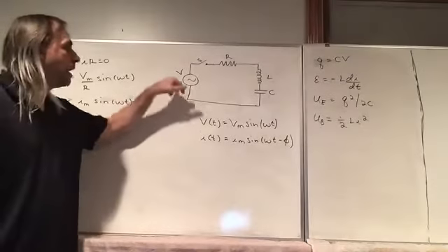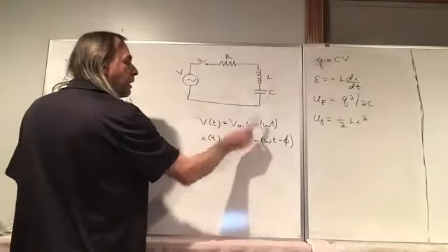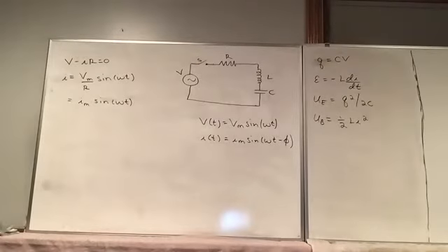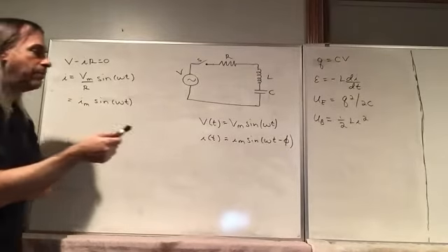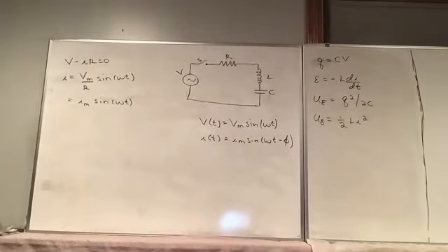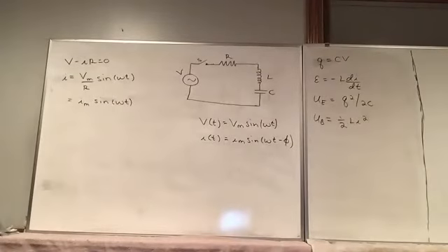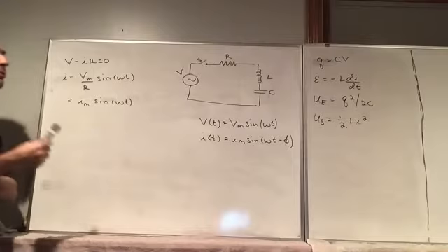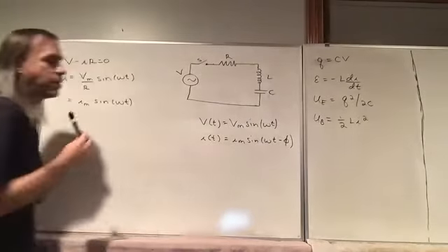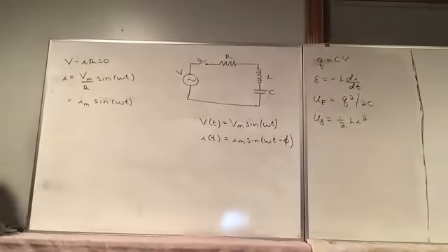And so if the power supply is driven by a sine function, so here we have a maximum voltage times sine omega t, which we get just by plugging something into a wall. I'm just going to state for now, where we can show later on that this is actually true, but the current is described by this equation. So we have a maximum current times sine omega t minus phi. And we want to be able to describe the current in the circuit. And so what we have to do is find the maximum current, and this phi is called the phase shift.